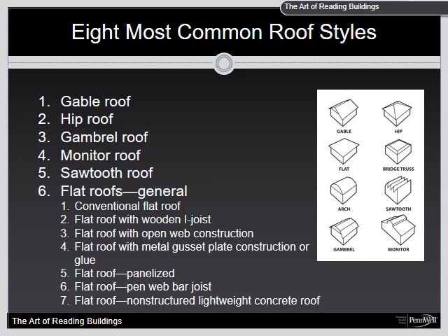The term gable is derived from an A-frame configuration. Two slope or angled surfaces between two flat ends. The two most common methods of construction are conventional and lightweight, or considered truss construction. Conventional construction is often referred to as stick frame construction, as this name is derived from the fact that each member is literally built stick by stick.